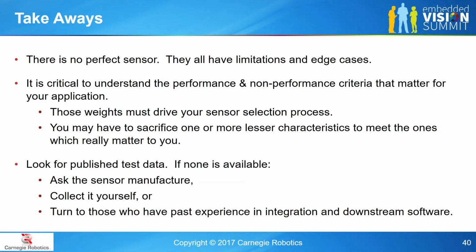And just because someone's using a particular sensor modality for one application and having success with it does not mean that when you put that same application in a different environment, or if you have a different application in that same environment, that you should be using that same kind of sensor. You really need to think critically about what you're doing with the data, how these sensors work, what the edge cases for these sensors are. Are you going to see those edge cases in the environment that you're operating?